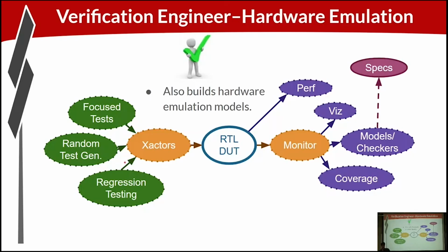TL Verilog actually potentially plays a very important role, since TL Verilog is modeling things at a more abstract level. The modeling methodology of TL Verilog is more appropriate for performance modeling than RTL would be. If you model these components, the transactor and the monitor, using transaction level Verilog, you're naturally synthesizable. So you can fit these components then on the FPGA as well, and thereby not limit the performance that you can get for hardware emulation.